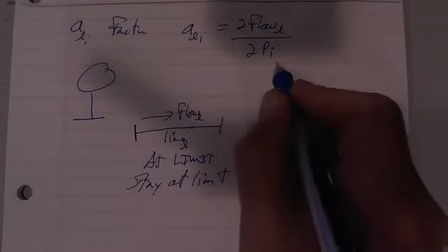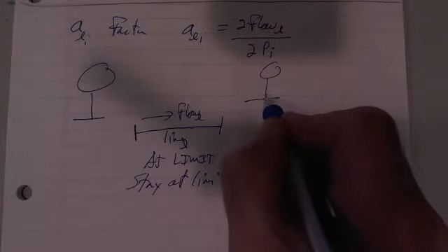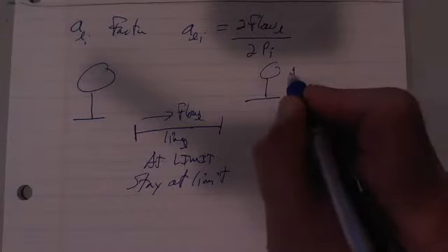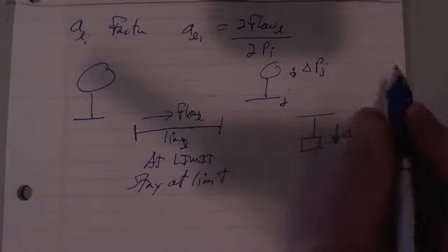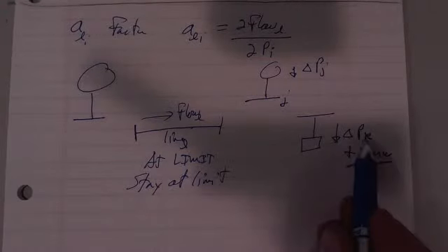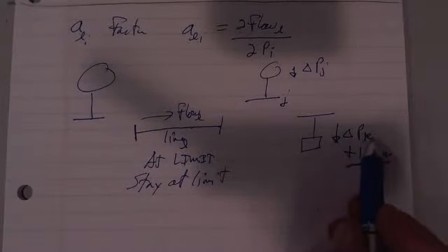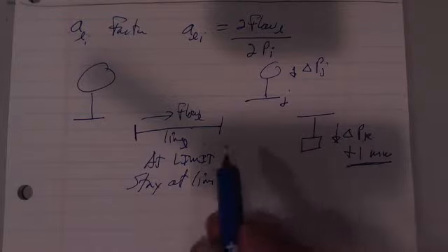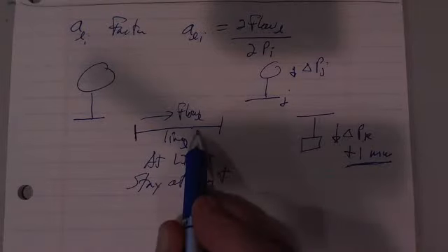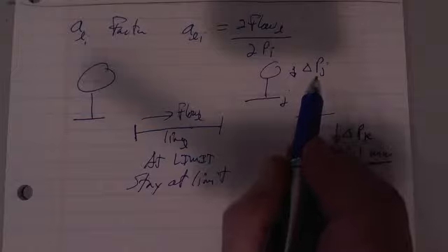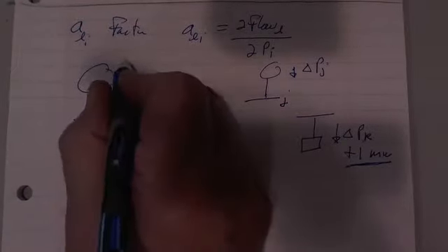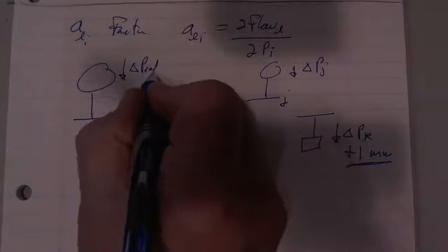And the only way to do that is to add another generator, to bring another generator in here called J, and say, well, then the change in this load here of 1 megawatt causes a change in the losses, and it affects the flow on this line, and this generator will adjust to keep the flow constant, and of course I get a delta P ref here.